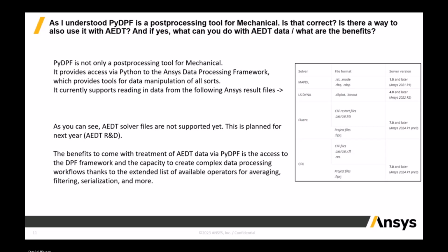And what can you do with AEDT data? What are the benefits? Of course, there's going to be a discussion to have between whether to use PyAEDT directly or whether you have some benefits to use PyDPF in addition to PyAEDT. The answer is PyDPF basically gives you access to the DPF framework with all of the operators and the ability to create complex workflows for filtering, serialization, and more. So we're also, of course, going to be developing specific operators for the kind of operations you would want to do on results from electromagnetic simulations. So this will most likely come with the support of result files from AEDT.